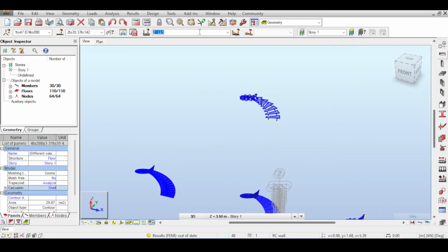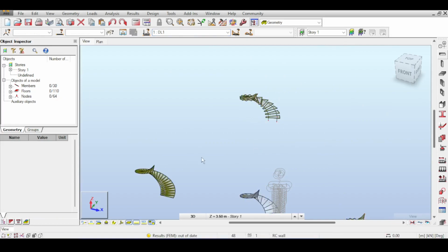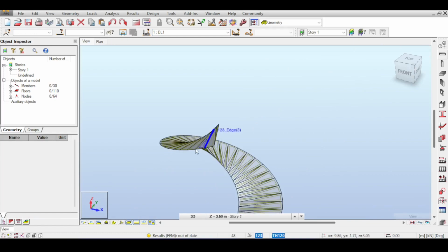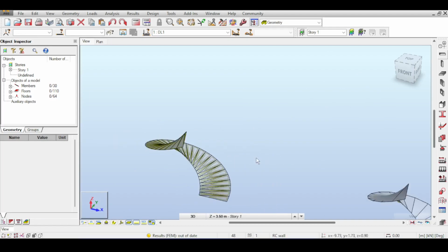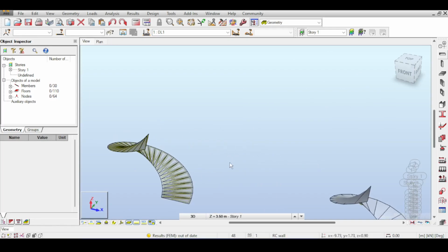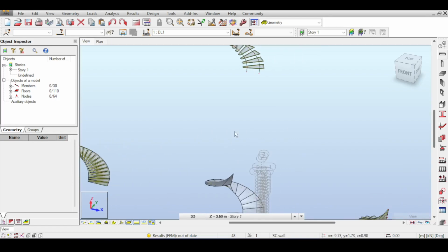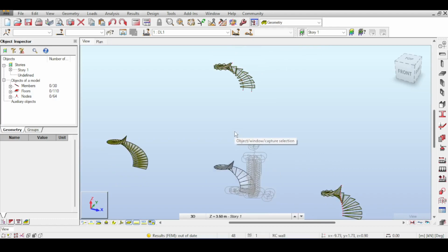So we go to our dead loads. I don't know, you have some covering materials. What are those covering materials? Well, you see, and this is important now, the dead load of this, the self weight of this, only covers the thickness of the slab, but there is the tread and riser, and there is also the covering materials on the tread and riser, because maybe you want to cover it with marble or something else. So you should take this into consideration.